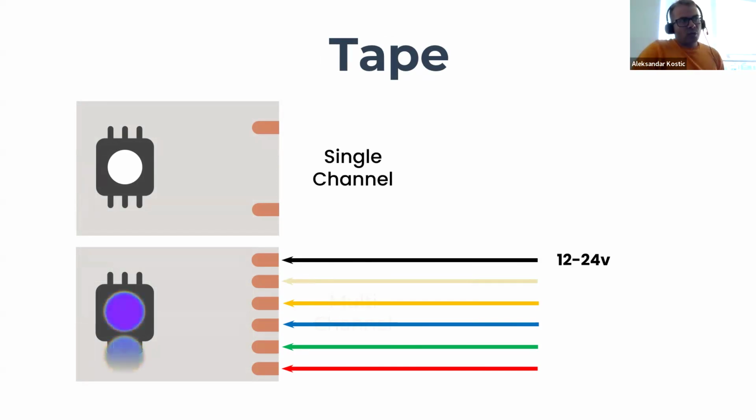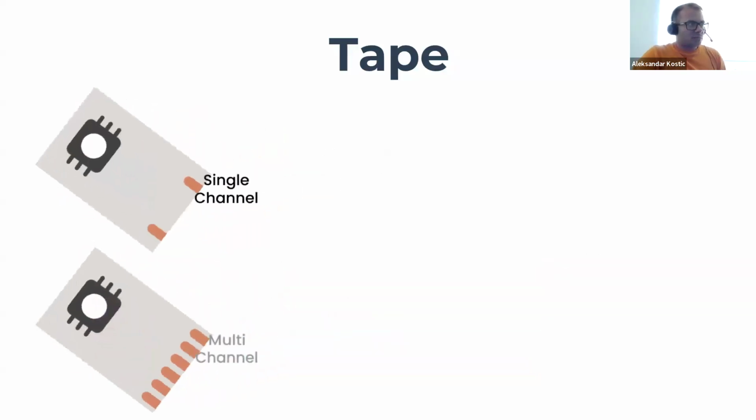Generally, LED tapes work on 12 to 24 volts DC. Everything we have under Vibrant LED tapes and the controllers as well works on 24 volts. So when we are setting up the Vibrant system, we are working on a 24 volt low voltage system.